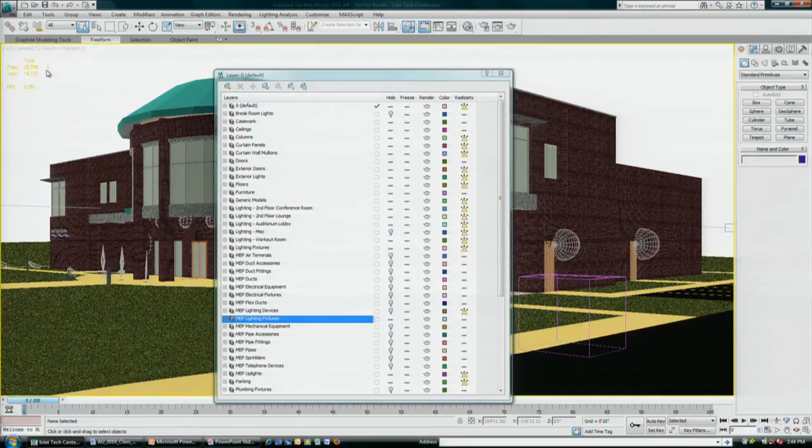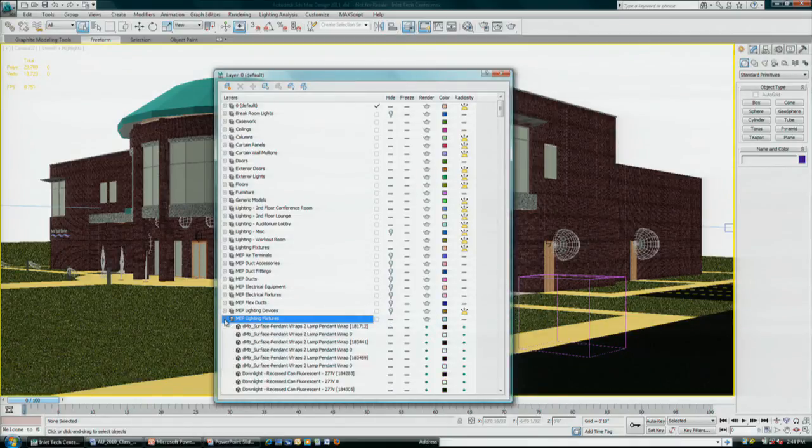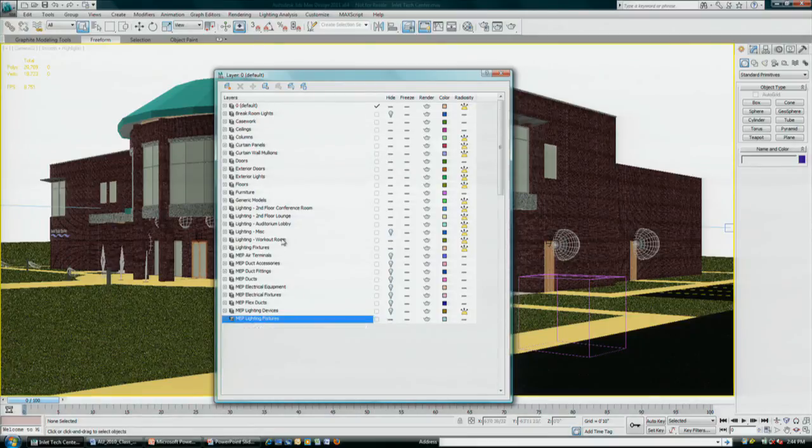And that's just lighting. I didn't take anything else out of the model. No structural work, nothing. The next step for me to get the render times down a little further would be to look at the structural model and what wasn't contributing to the scene. Because you've got all these wraps around your columns, you can take the columns out. If you don't see the footings, you can take them out. So we can take out a lot of information and just container it off temporarily while we're waiting for those render times.